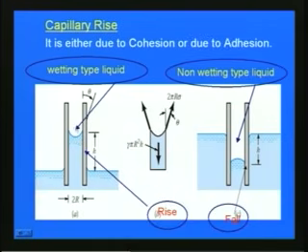So, the liquid is, you can see, wetting both surfaces. That is why, due to the cohesion, a rise is taking place, and that is what is called capillary rise. But in the case of non-wetting fluids, like for example mercury, if you put mercury in a bottle like this and then put a small tube, then you can see that it is falling down.